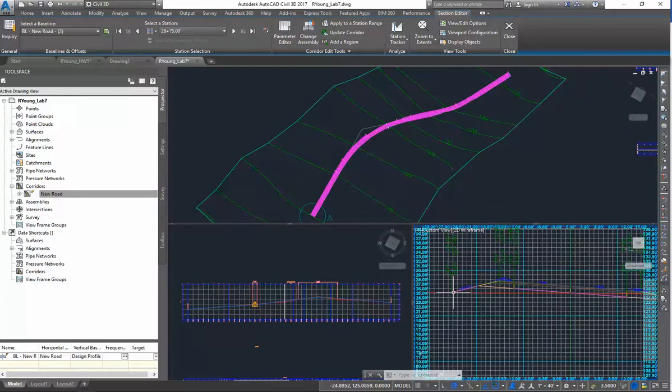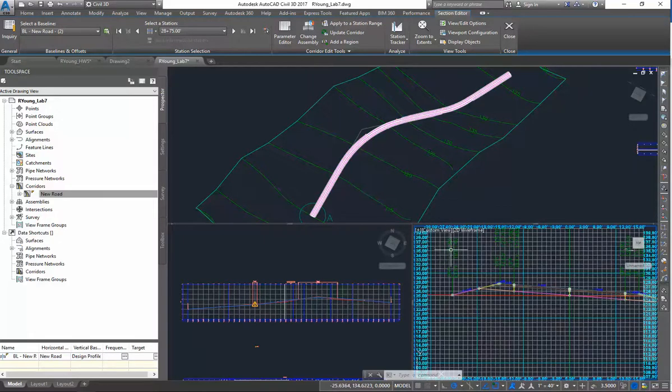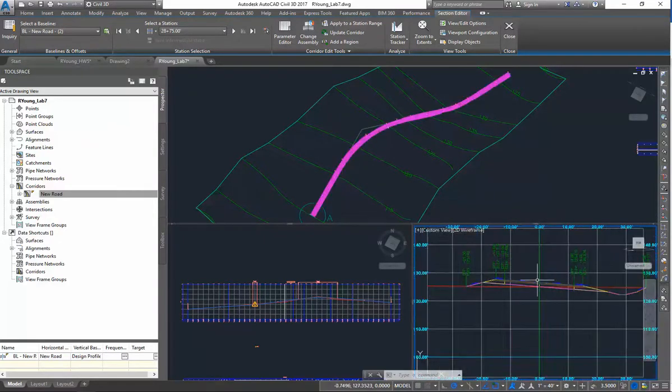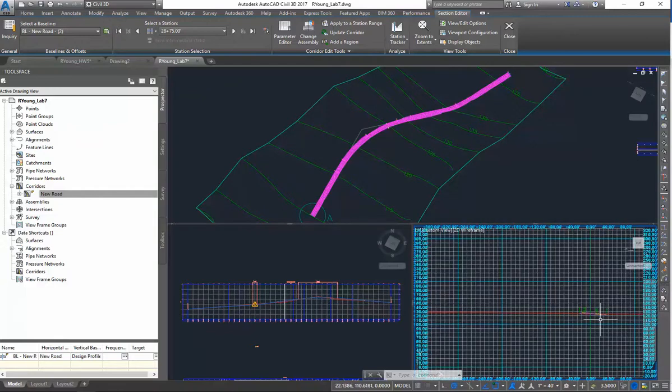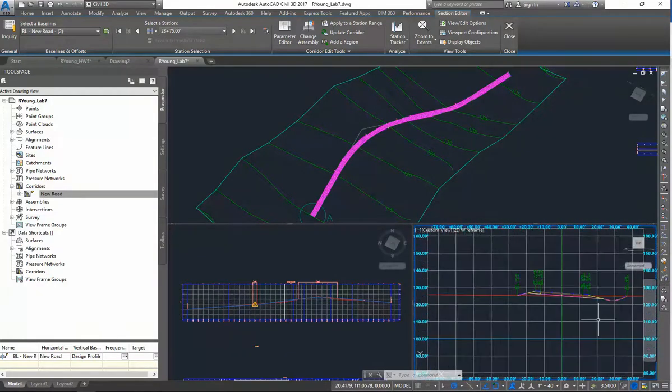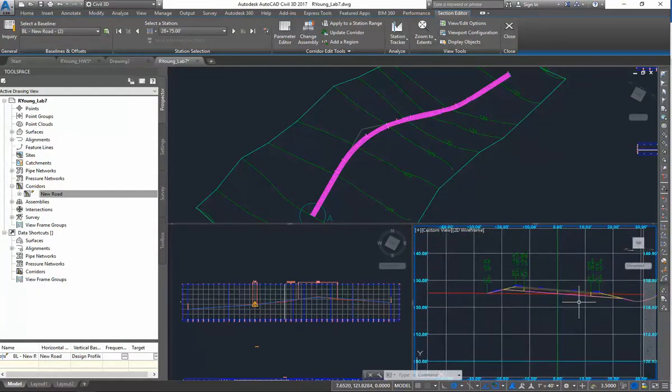And so it tells me where my offset is, that I'm 25.3 feet off of center line. Remember, I have a 12-foot lane. I have a 3-foot shoulder to here. I have my shoulder taper, and then I have what we call the daylight line, the point where my engineered section intersects with my existing ground. So I can see that.